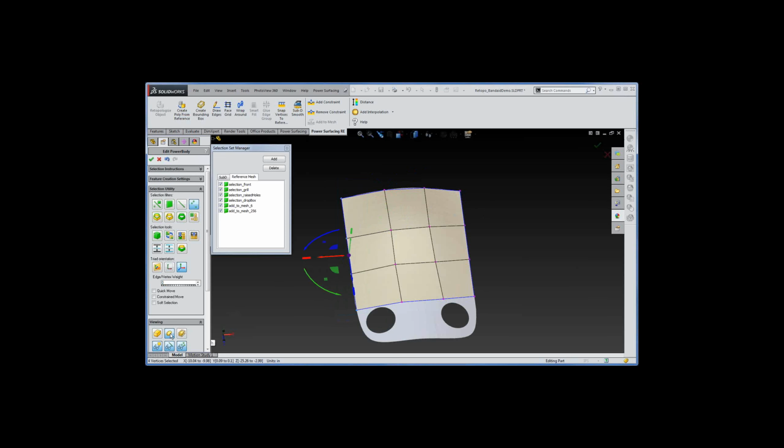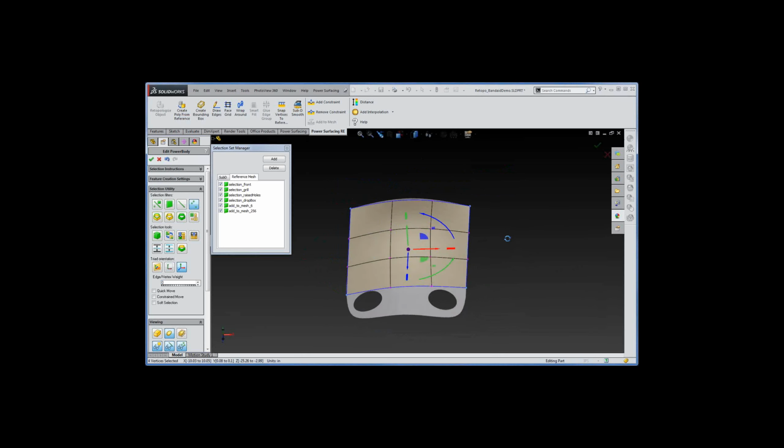And if I switch this over to SubD display, you'll see that we've got some rounded corners, because rounding off is what SubDs do. But we can go ahead and select these guys and make them fully weighted or hard edge. And now they stick right down.